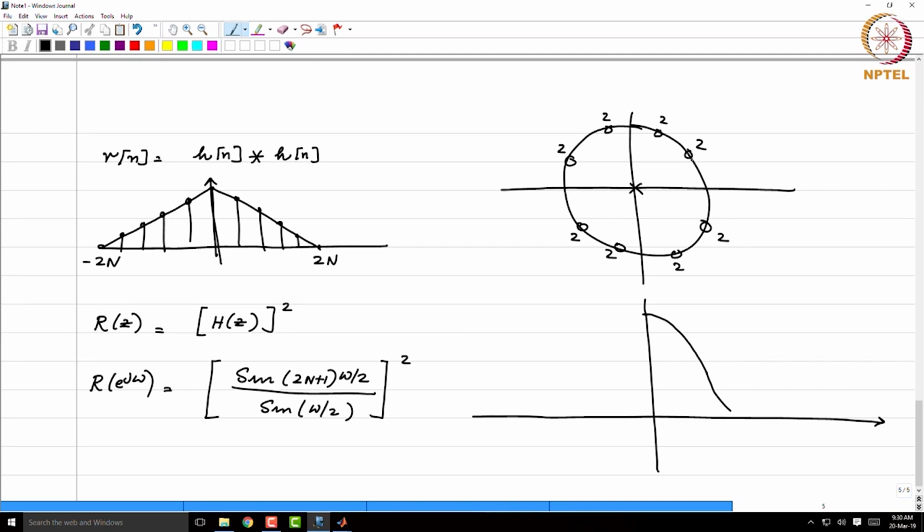When you cross a second order 0, the total phase change will be 2 pi, and a phase change of 2 pi is no sign change, and hence the frequency response will become 0 and again go back up. So, this is how the frequency response will look.